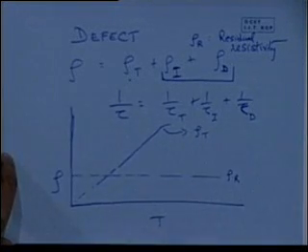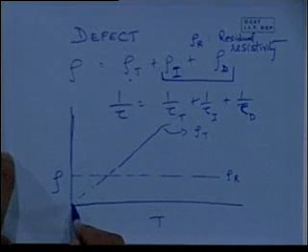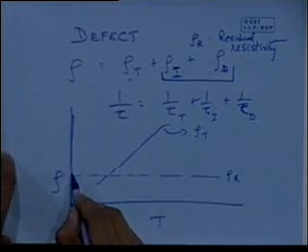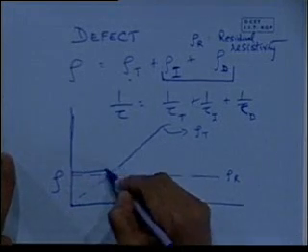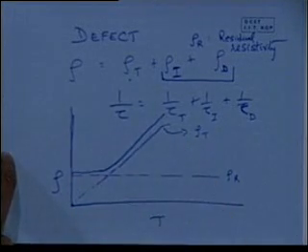So what will I expect of the overall resistivity in a material in which both these kinds are there? Mathiessen's rule says that I simply add up these, right? So at this point, what will be the resistivity? This plus this. So right there. Then it goes somewhat like this, and then we expect it to go something like this. It's not exact, but of that nature.